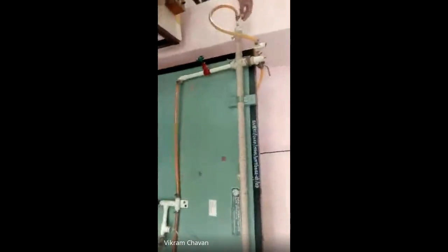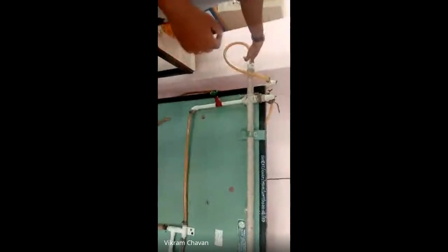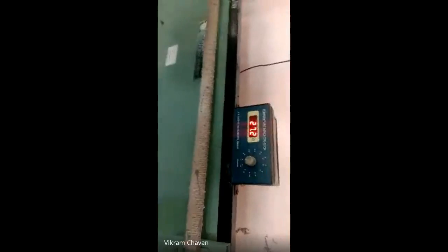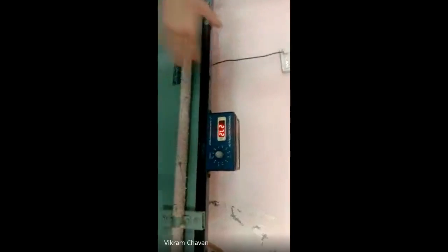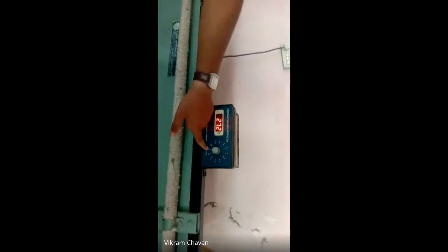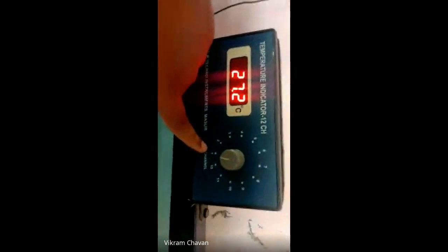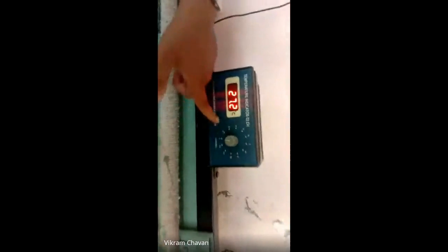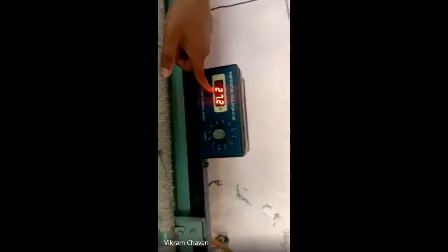Here you can see that one tube is placed in another tube, and through the inner side tube the hot water is flowing, and through the outer side tube the cold water is flowing. So now here we have to consider the reading for parallel flow arrangement. First of all, we can take the temperature reading. Directly from first reading only you can take the temperature reading. So T1. Now here you can see that the knob is placed on T1. This is the temperature indicator, and it is placed on T1. T1 temperature is 27.2 degrees Celsius.